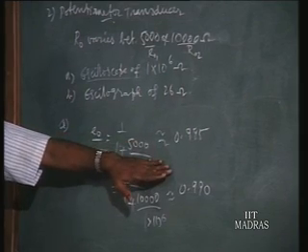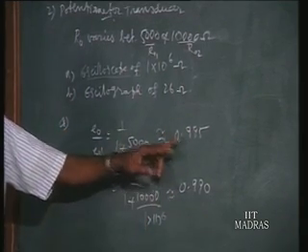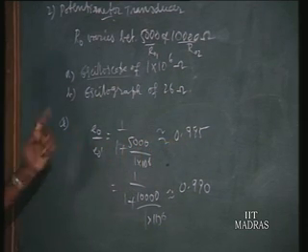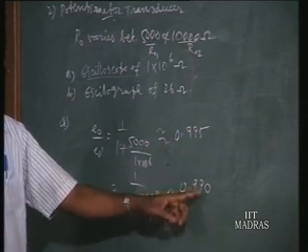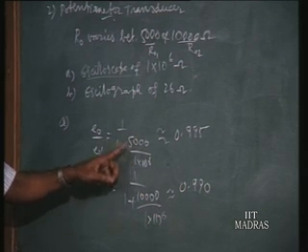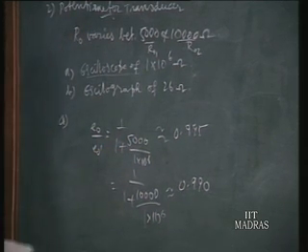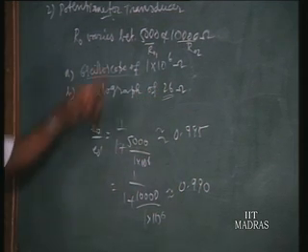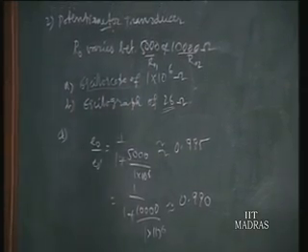So when the input resistance is more than 100 times or something like that, though the loading effect is varying, the actual output voltage is near about the actual theoretical voltage, because the loading effect becomes very negligible, though varying. What is varying? Only the third decimal. It is because the input resistance is very large compared with the output resistance of the potentiometer transducer. But when the input resistance is small, this varying output resistance effect is magnified. That is the case now.